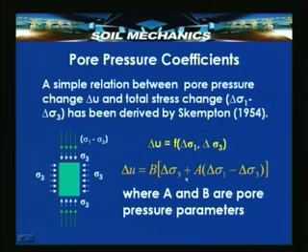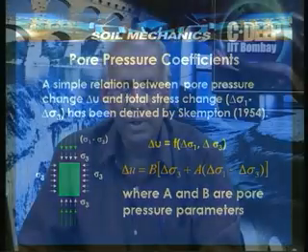Now, the constants B and A are what are known as Skempton's pore pressure parameters, and those are parameters which are very important to know. If you know those parameters for a given clay, then it is possible to make a reasonably good guess about the change in pore pressure due to change in stresses. This is a very important convenience when it comes to solving or addressing practical problems, where given a stress change, you will be able to predict what will be the change in pore pressure that is likely to occur.